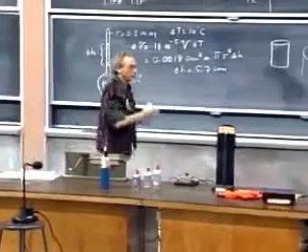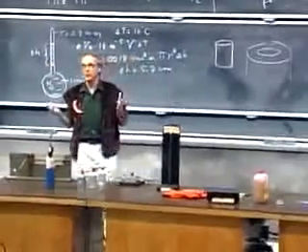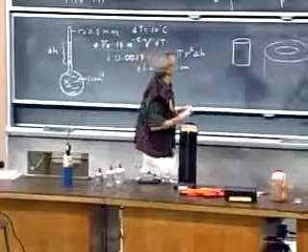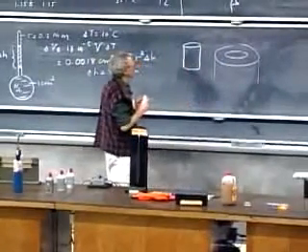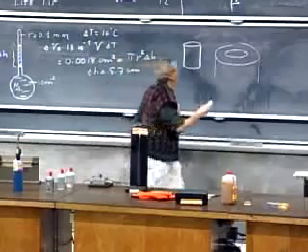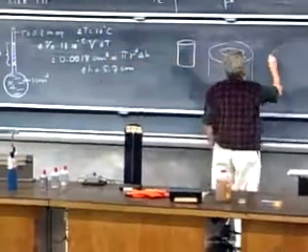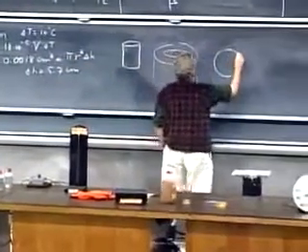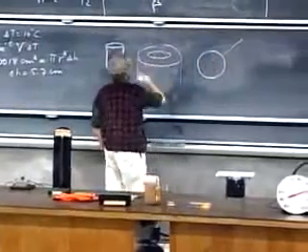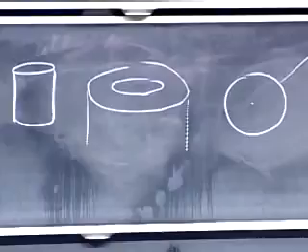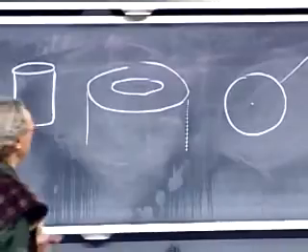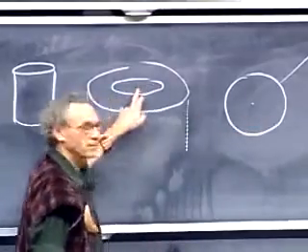I have something to show you here which is the opposite of shrink fitting. I have a ring, I'll show you shortly on the screen there, and that's made of brass. And I have a ball which goes through there, just barely, but it goes through there. And then I will heat up this ball, and then it won't go through there.